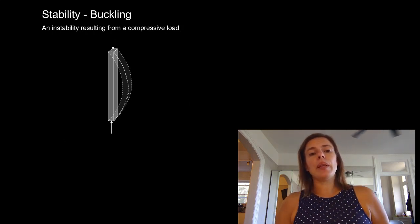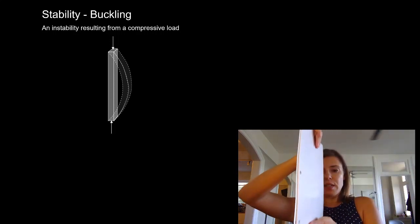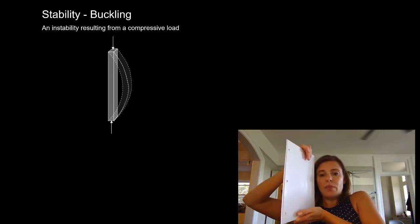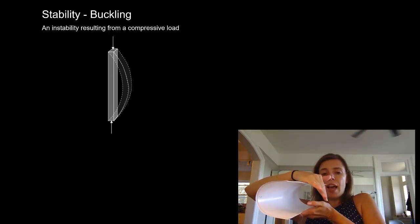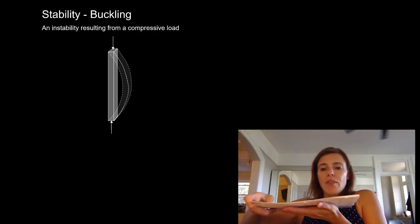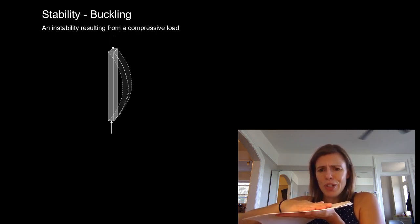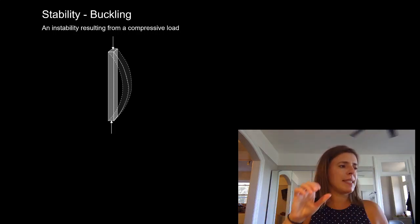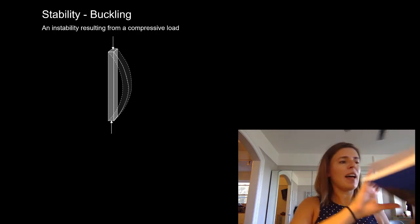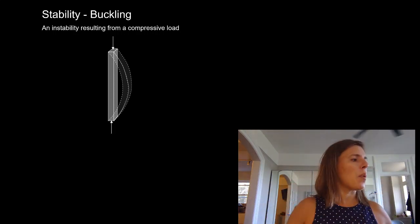Buckling is an instability problem. That's when we're pushing on something in a compressive load. So here I have a piece of paper. If I try to crush that, it takes almost no force. It tries to buckle. If I do the same thing with the paper in this direction, I'm just pushing on paper. It's like I'm pushing my two hands together. Or, it's a little bit easier to see like this. We're not worried about buckling.